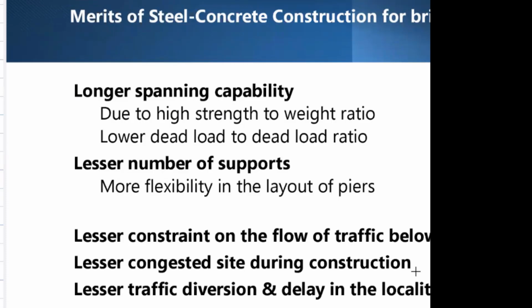Now, if you take a span for concrete and compare it with steel concrete composites, possibly it is not a right comparison because of the lower dead load. The spans can be a little larger in the case of steel concrete composites, and if you have enough headroom, we can also go for the trussed composite bridges, which we have one in Mumbai.